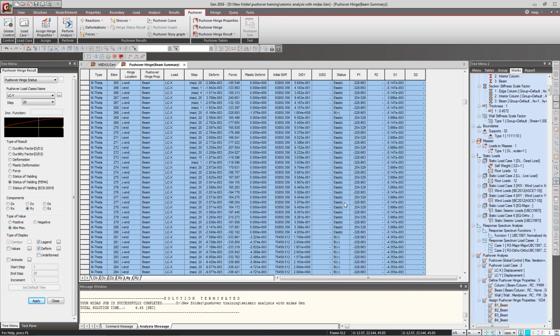From the diagram, I didn't observe any beam exceeding life safety, so maximum I think we will get is immediate occupancy plus. So none of the hinges in the beams are exceeding the life safety level, so should be acceptable, unless it's a hospital or some important structure, or unless the investor wants to design it for below immediate occupancy. So beams are all okay.